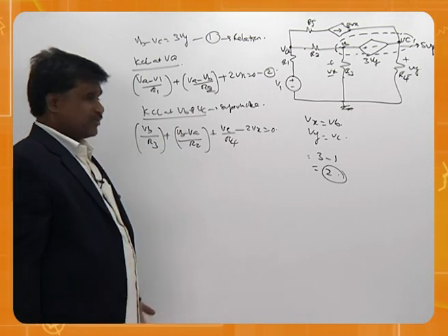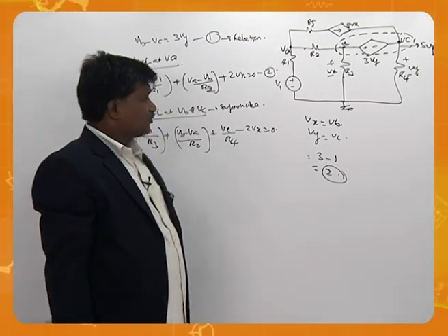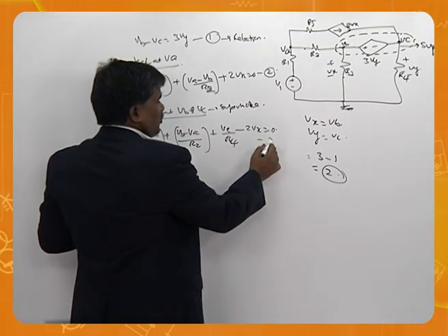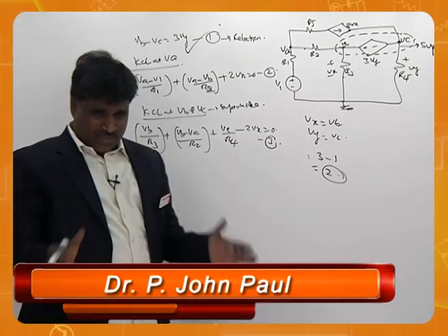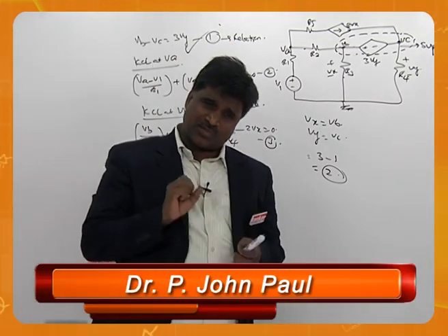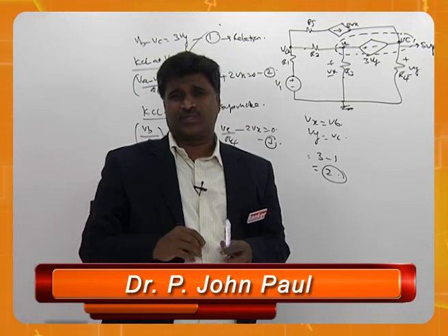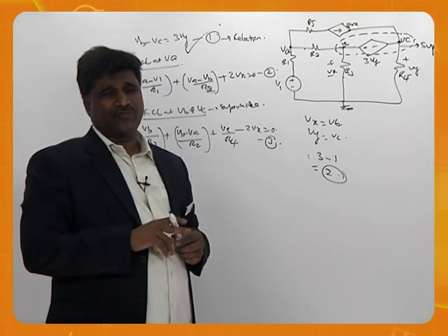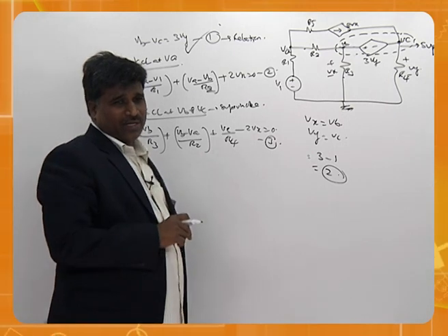So please look at that way how the solution is going to come. So these are the 3 equations, but out of which one is a relation. So when there is a voltage source, normally people think they should go for KVL, but we are going to go for KCL, by which we are going to do it much faster. This is about nodal analysis.